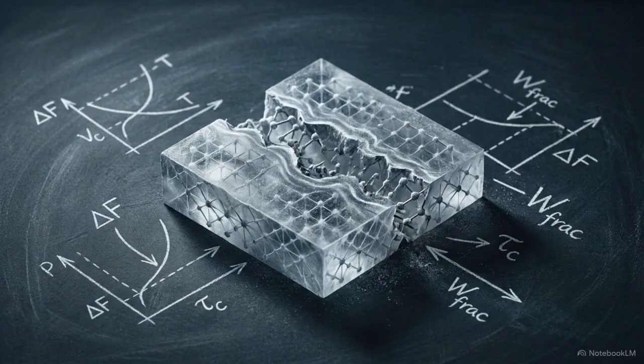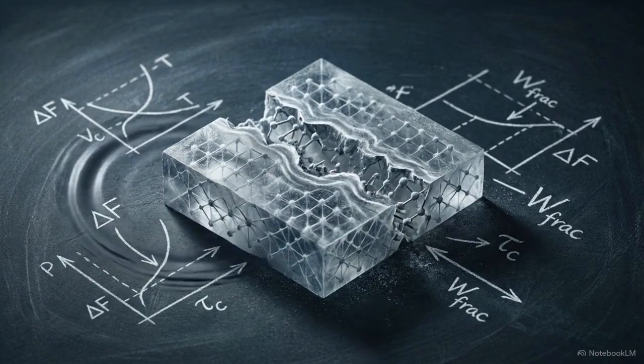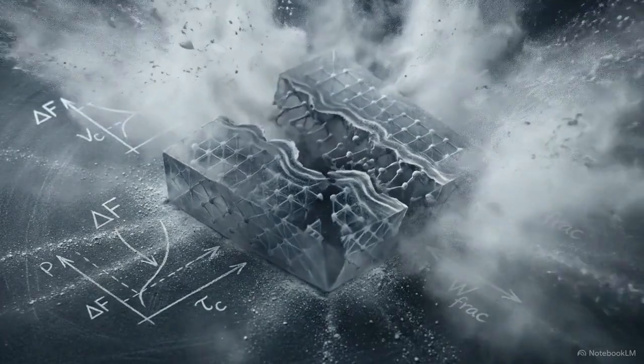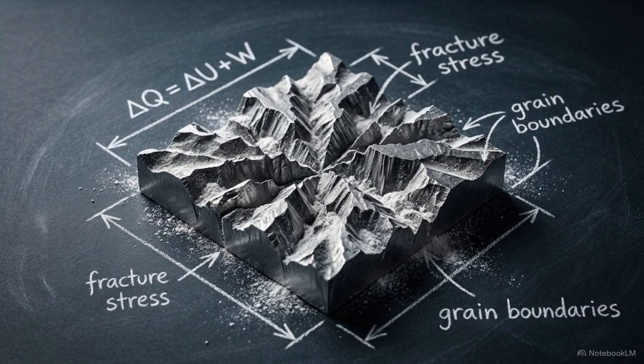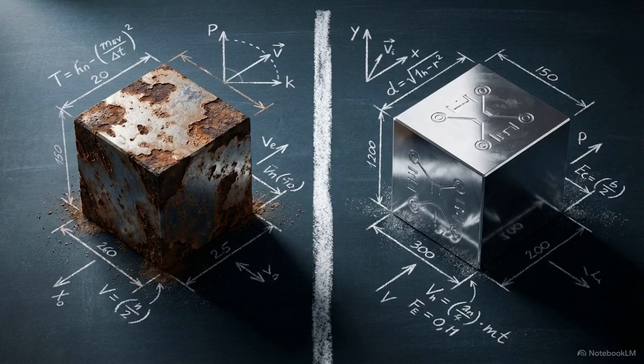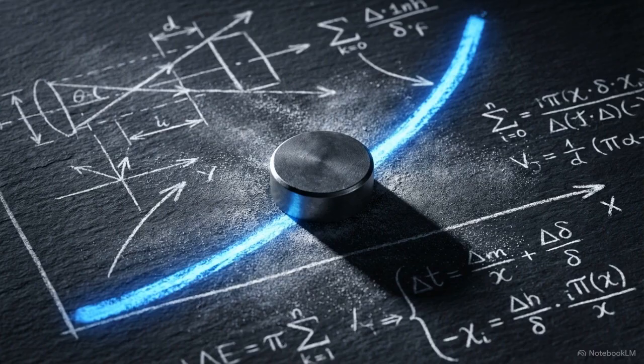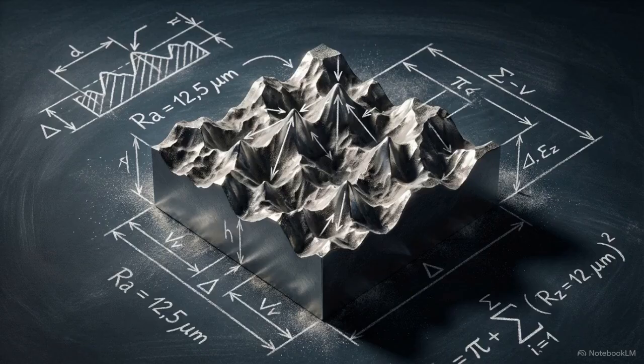Normalized energy is the quantification of the thermodynamic work required to initiate the first crack and propagate the debonding wave across the interface. By focusing on energy rather than raw force, engineers can mathematically account for variables like prior surface treatments or active state corrosion that would otherwise skew the data. This integration of optical metrology and computational modeling elevates adhesion testing from a simple mechanical break into a precise, predictive thermodynamic measurement. Ultimately, all of these methodologies serve one function.